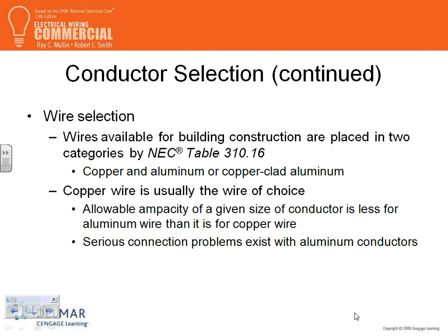And a couple of other things, guys, is number 12. No matter what you do, number 12, you cannot break for lighting purposes. You cannot break number 12 with more than 20 amps. If it's number 14, drop number 14. Don't even think 14 when you talk about commercial. Don't even think that word 14.